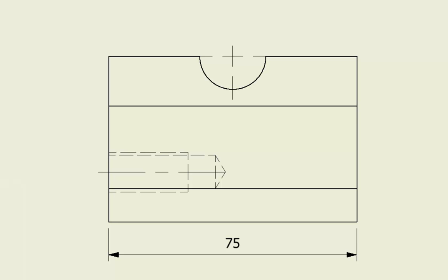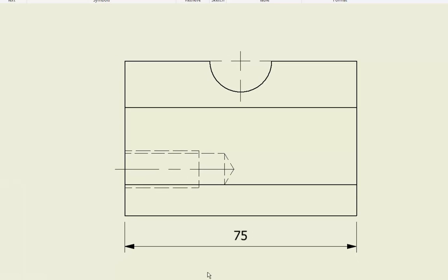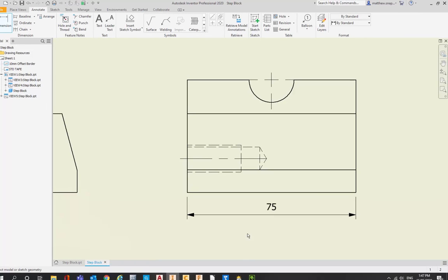And because we're actually working on the sheet, if this is at scale, it will present the true dimension of the object, but all the features of the dimensions, the height of the text, the offsets, the arrowheads, all that sort of thing, will all be at the proper scale for plotting on paper. So it works really well, it makes it very easy. So that's just a straight linear dimension.